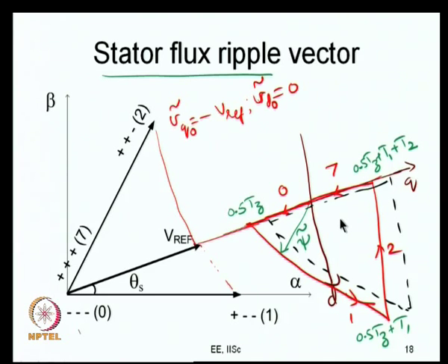your THD is minimized, but that is not the case when, let us say, you have 1/6 or some other third harmonic, when the percentage of third harmonic added is something other than 25%. Alright. So, let us just stick back to our conventional space vector PWM for the time being now.